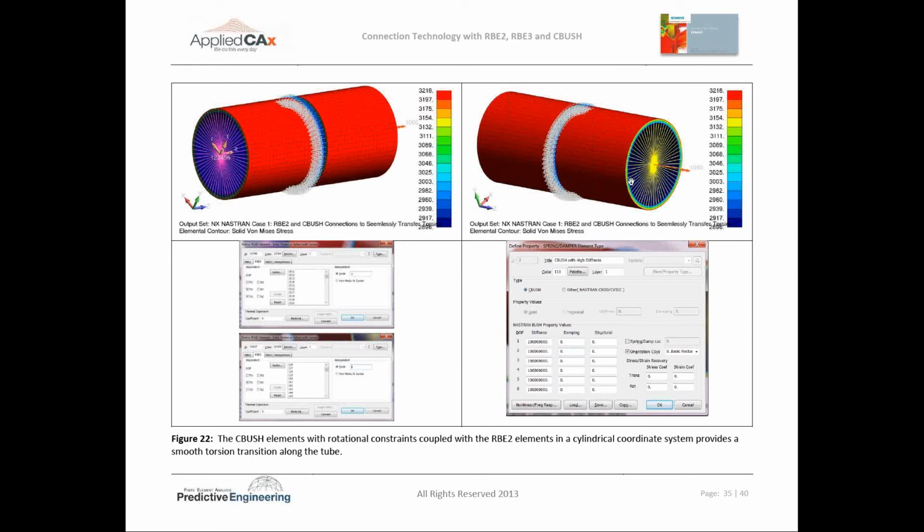I'm applying the loads on both ends with the RBE2. Because if you use an RBE3, because of the weighting function, you would actually have to change the weighting functions as a value of R in distance out here to the independent node. It can be done, but I sure ain't going to do it.